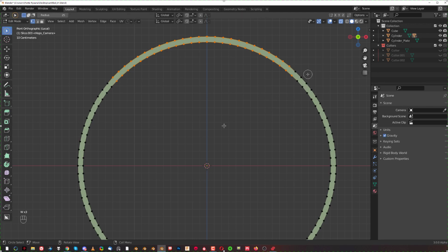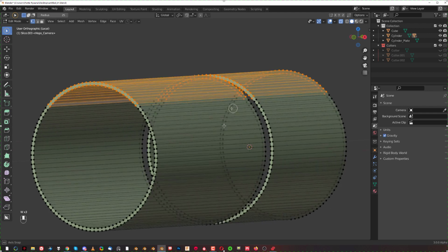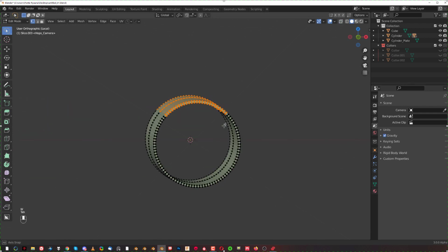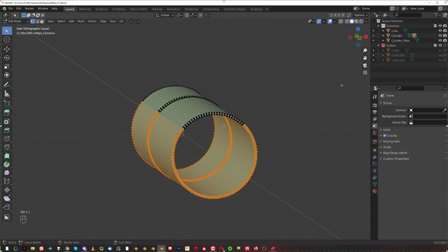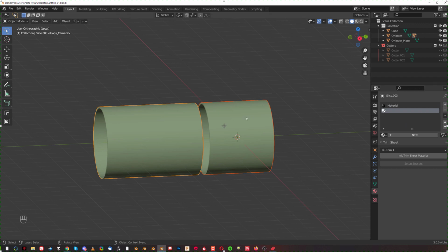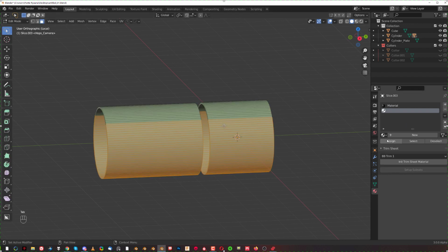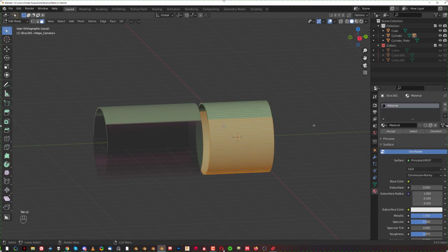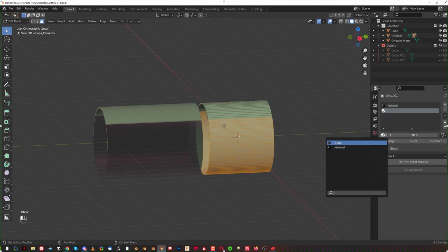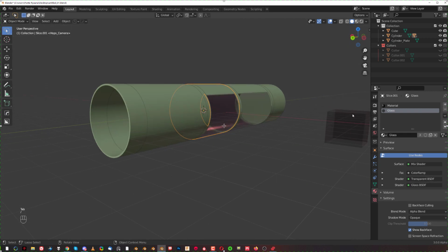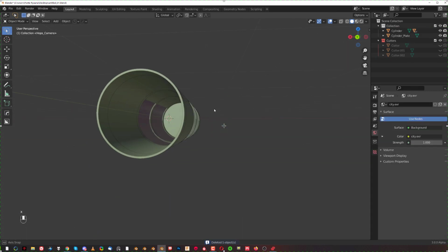So press W a few times, hold shift and select them, and then you're gonna select all these verts through here. You can turn off pass through, Control I to invert it, and let's go to material and add material, and go to edit mode, select the glass and assign, okay? And same here, add material, glass, and assign. Cool. So we now got glass on the bottom. We don't need this. We can delete it.